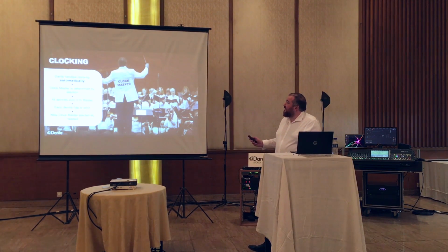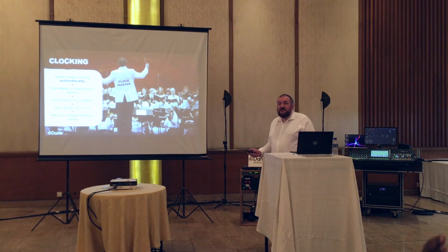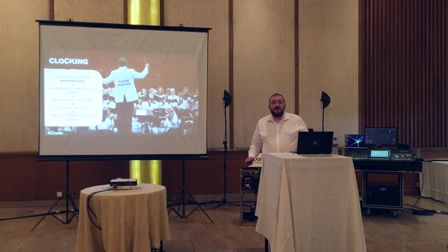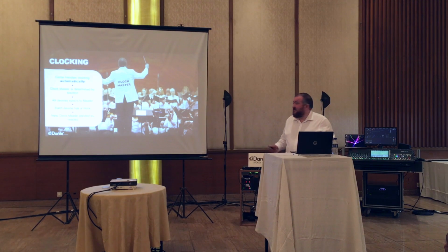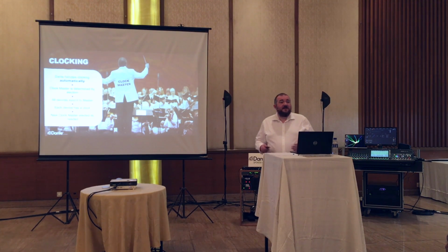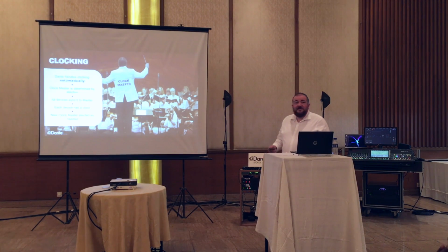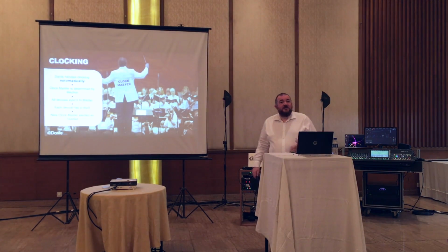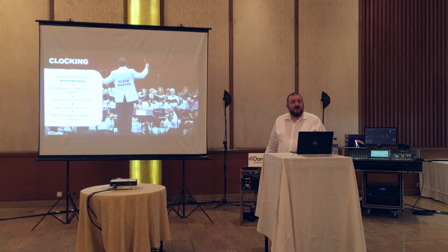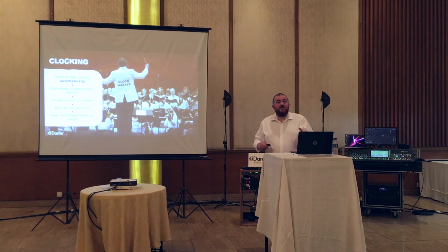So clocking. Dante handles clocking automatically. We use a standard called IEEE 1588, and the master clock is determined by an election, and the criteria for winning this election is well defined in the standard. All of the devices will sync to the master clock, and each device in turn has its own clock as well. And that means that if the master clock goes away, the network can elect a new master clock. And the nice thing with our implementation on Dante is, while that master clock election process is going, because all of the devices are very well synchronized with each other, you can change the master clock and you won't hear that change happen.